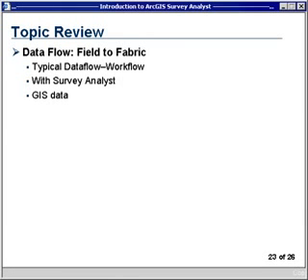And we know the typical flow is from the field collecting data into a survey package to resolve coordinates, into a CAD system for drawing, and then export to a survey system or to a GIS system. Well, with Survey Analyst, you can go right from the field, right from the measurements, into the GIS system. And the impact of this is that now we have a new data layer in our GIS. We've got raster data, vector data, and now we have survey data.